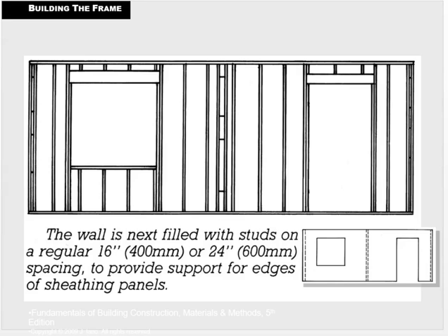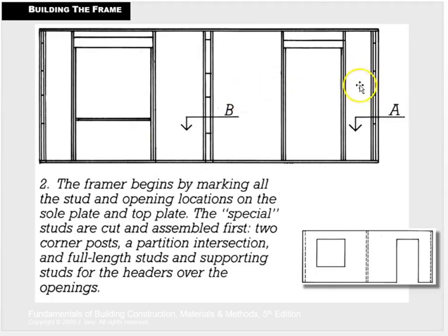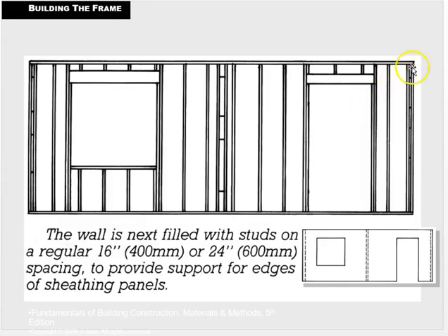And then the remaining studs are brought in all 16 inches on center. So that's starting from this outside location. So if we kind of flip back and forth, we can see where the voids are. Void, void up here, no studs, void, void, all void across here and void there. And then when we jump forward, we see we pull our tape measure here at 0, 16, 32 inches, 48 inches, and so on.